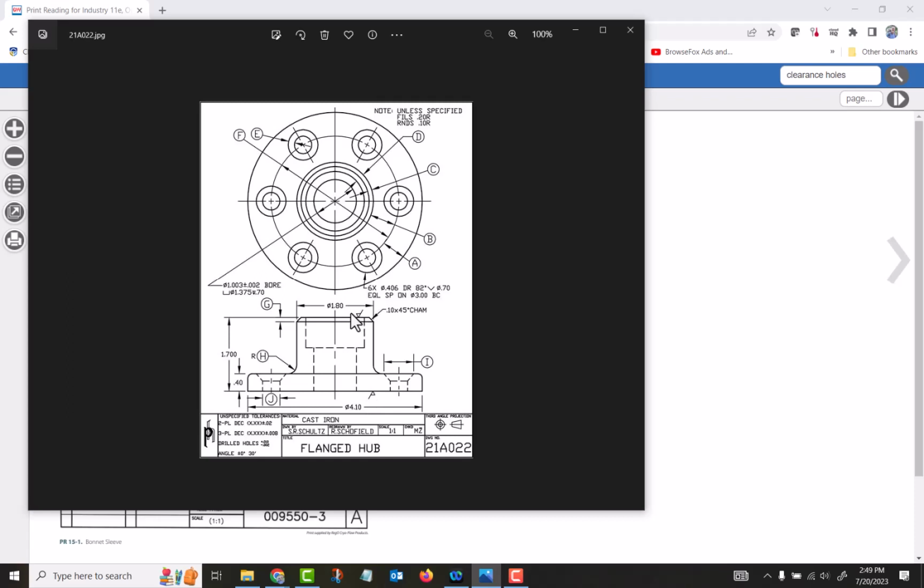That means there'll be an additional 1/8 of an inch on both sides, because it's an 1/8 of an inch per finish mark. That's on the casting, and so that gets machined down, so we get a nice overall height of 1.7. I put that in Blackboard for you as a reference there. It's typically 1/8 of an inch, or 3 millimeters, the metric equivalent of that.